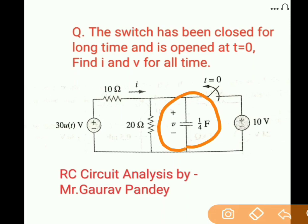Whatever transient and steady state response we will be discussing, that too will be with respect to the capacitor voltage. So in this circuit, if someone asks you what the state variable is, the state variable is the capacitor voltage. The number of state variables is only one, that is the capacitor voltage.